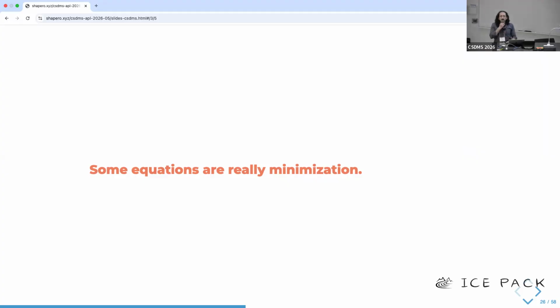So the simplest minimization principle is for elasticity, where when you're solving the equations of linear elasticity, really under the hood, you're minimizing the elastic energy of the displacement. This is funny because viscous fluid flow is a dissipative problem. And so it strains belief that it should also have a minimization principle, and yet it does, and we can do cool things with this and write better code.